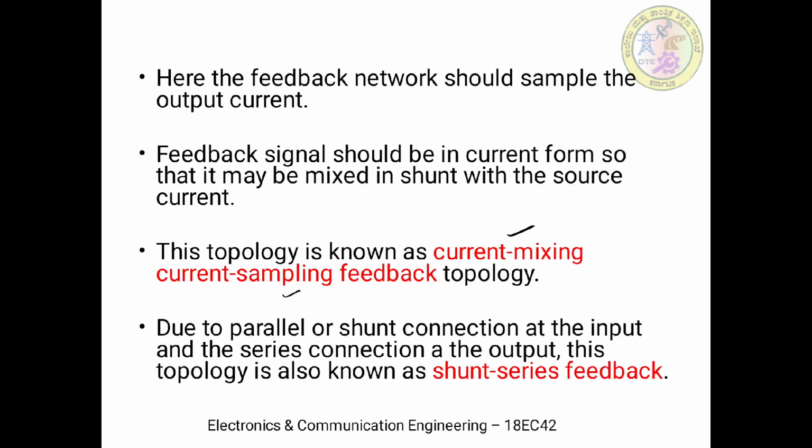So this particular topology is identified by a particular name known as shunt series feedback. The word shunt refers to the input side, and series refers to the connection at the output side. Because of this connection pattern, this topology is known as shunt series feedback.